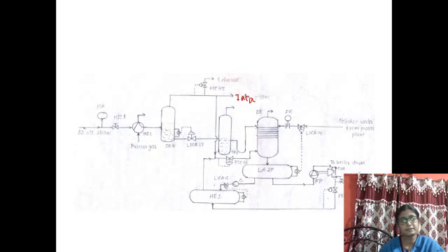But from a part of the plant, 53 atm steam is generated. That steam is used to drop the pressure in order to generate 7 atm steam through a certain separator unit. Two separator units, SR4 and SR3, are shown here, but in a real system there exist a number of separator units.